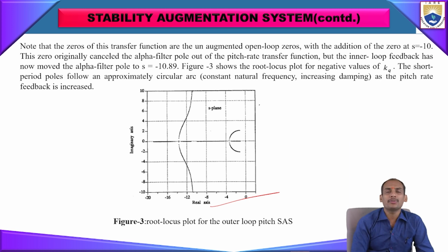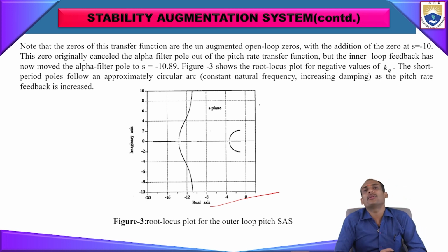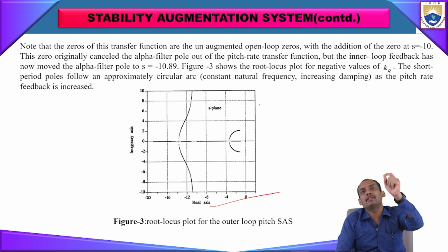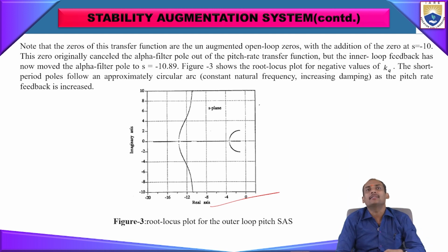This is the transfer function for this root locus program. Here in the root locus we are solving for the s values, and these s plane values contain imaginary and real values, because we get complex values from solving that equation. So the imaginary values we take on the y-axis and the real values on the x-axis.